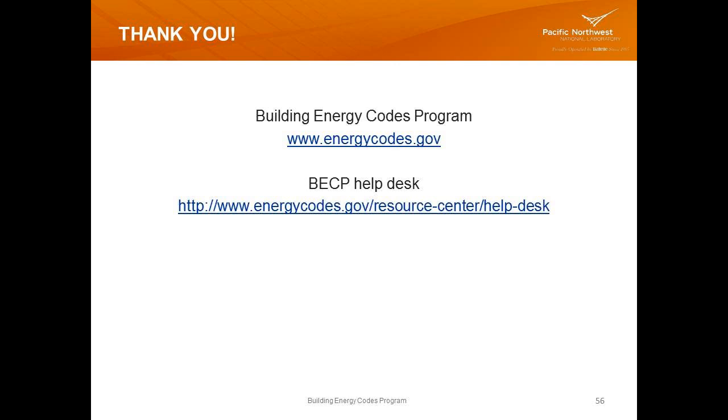And if you agree to do that and put that in your plans, then you're allowed to go to 40%. If you don't want to do that, or you want to go above the 40%, you then have to revert to using the 90.1 code, and that code from 90.1 has to be the companion one for the year of the IECC that you're associated with.